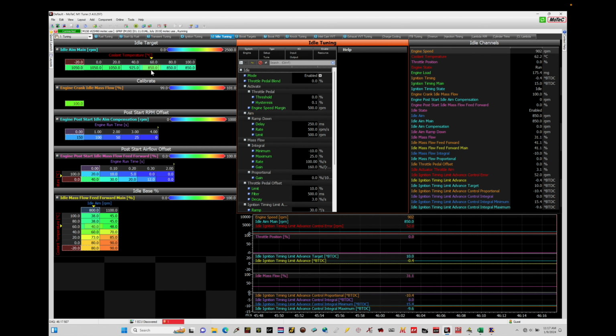If we're finding that we have more torque in idle conditions, the engine speed will naturally raise up. It'll go higher than our desired target here. If we have less engine torque, the engine will idle lower and will be lower than the desired idle speed. So what we find within an idle control routine is that we're influencing the engine's torque to hit the desired idle speed that we're asking for here.